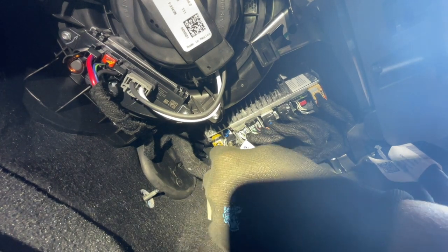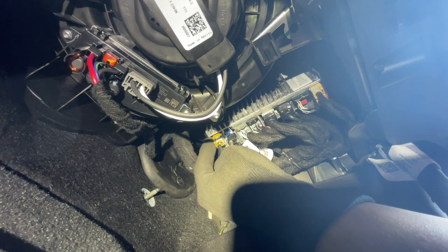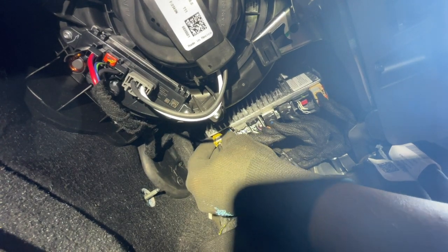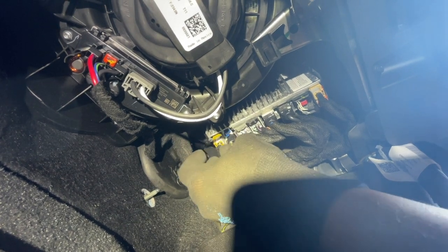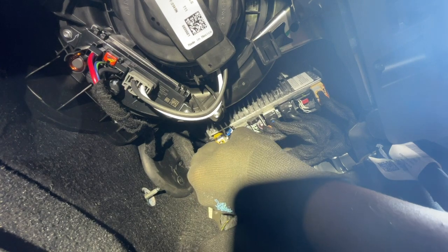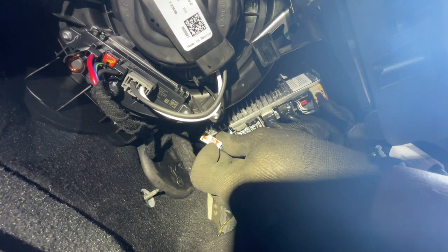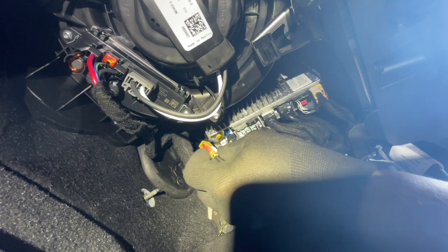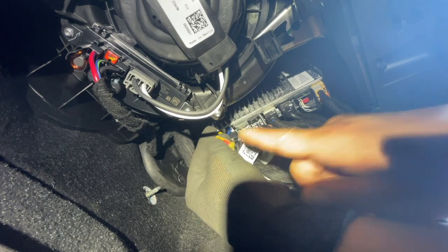So starting with the far left, I don't know, light green olive color connector. On the left side, there's going to be a red release tab. You need to pull that release tab down. Just like that, you hear a click. And then here on the side, there's a little tab you want to push in, and then you want to remove this connector. So there's the red tab, slide that all the way down, and you want to push in right here on the edge of this connector to remove that one.